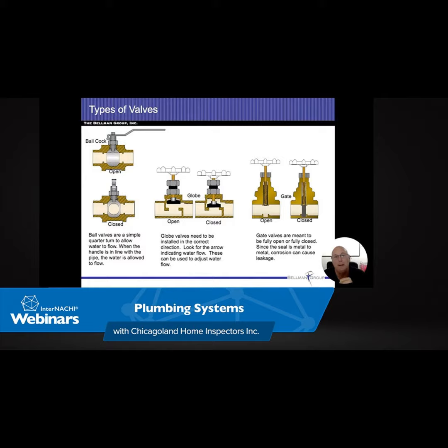We work our way down. Let's go over to the gas pipes here. So we do have a gas valve. We do have our gas pipes. We do have a drip leg coming in there. I think those are somewhat self-explanatory. The burner is at the bottom. If we look on the left side of the picture, that's going to create our flame, heat up the bottom of the tank, and then those hot gases are going to go up the center flue, up the center flue of the pipe until we get to the vent connector.